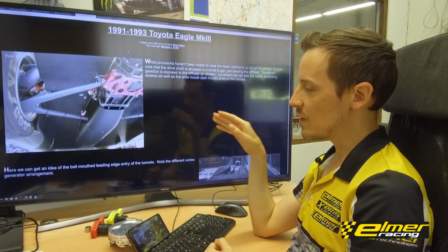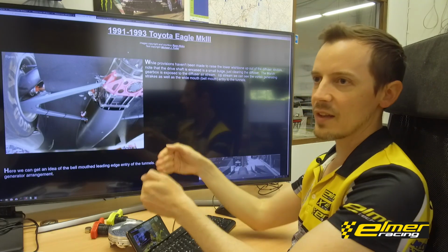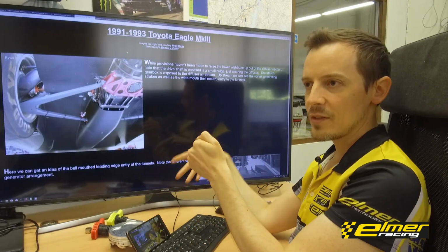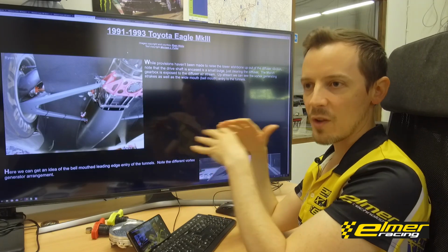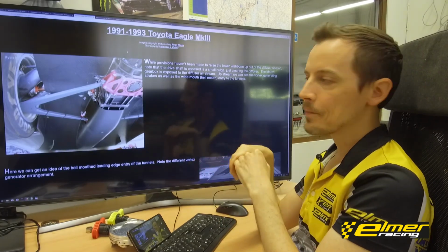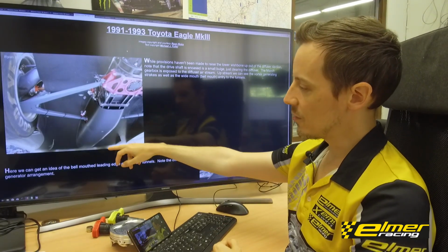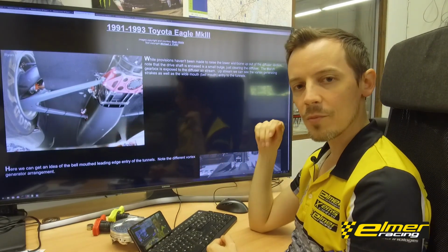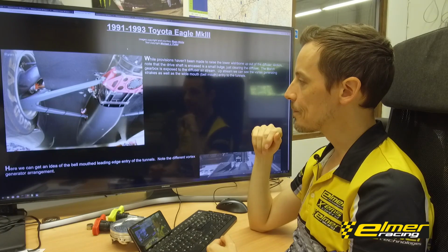And that is of course very important, because the more you can slow down the air to the rear of the car, the more your ambient airflow around the rear of the car will aid in the suction, and that will increase your flow velocity underneath the front of the car and in the diffuser where you're producing downforce because of that.